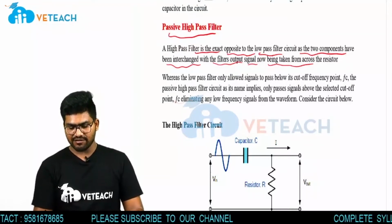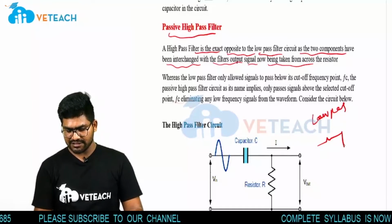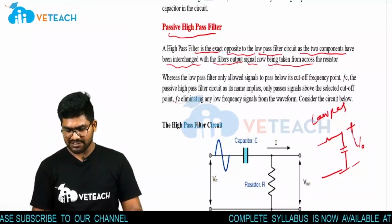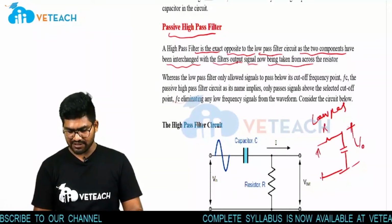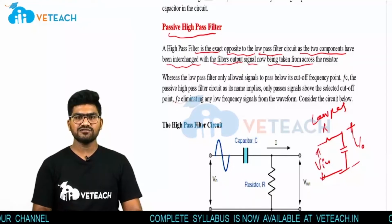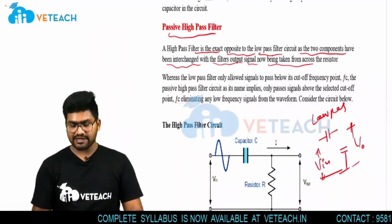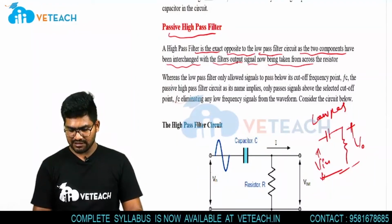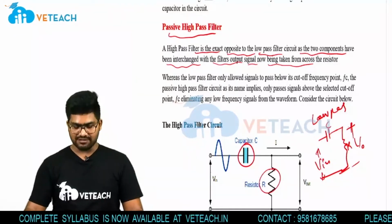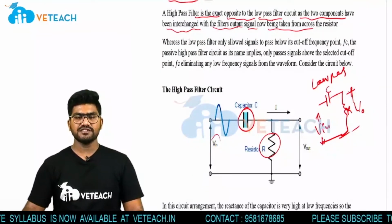In the earlier low pass filter, we had a resistor in series with a capacitor, right? We take the output voltage across the capacitor; this is R and this is Vin, the input voltage. Whereas the high pass filter is completely opposite to the low pass filter. Now in the high pass filter, I'll connect the capacitor here and the resistor at the output like this. Here it is the capacitor and here it is the resistor, and across the resistor we'll take the output voltage, and this is the Vin, which is sinusoidal.